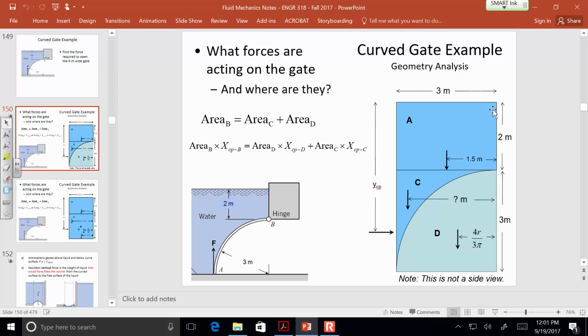And so the force of the shape is going to be proportional to its area and proportional to its volume. You'll notice here on this slide, I was giving you this weighted average system on the basis of area, but on the board, I wrote it in terms of volume. It's because we're finding the location of that force by doing a weighted average, and it doesn't matter if you average it on the basis of force, area, or weight, because the ratios are the same. The ratio of the volume of D to the overall volume of B is the same as the ratio of the areas and the ratio of the forces. So the whole reason why we did this part is to find out where the force is located. So you see this question mark M, how far from the right edge, because we need to know the moment distance in the end.